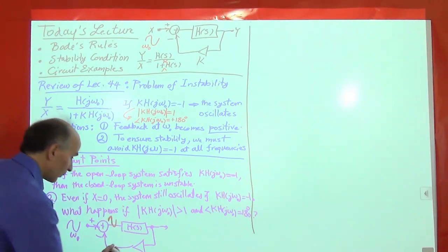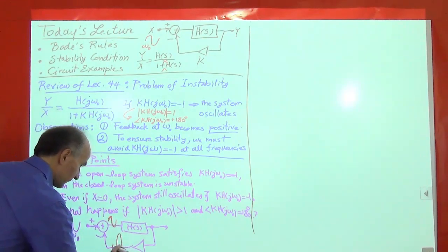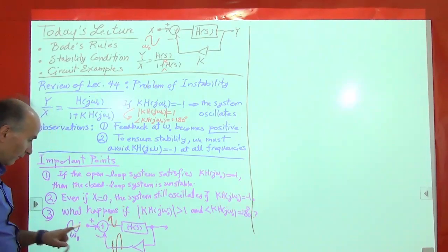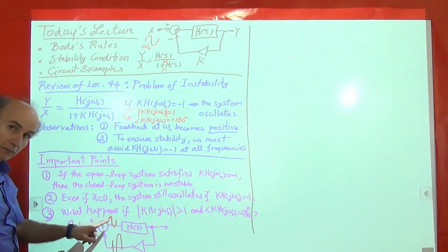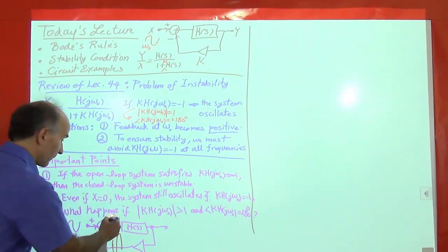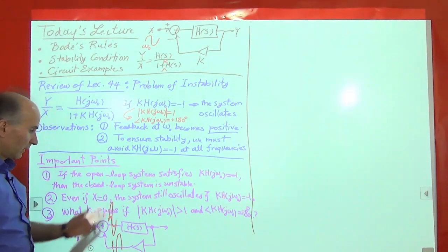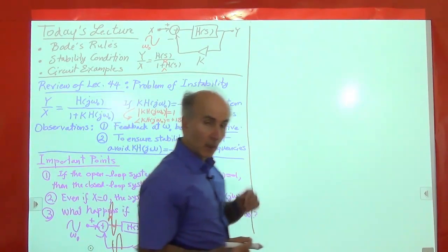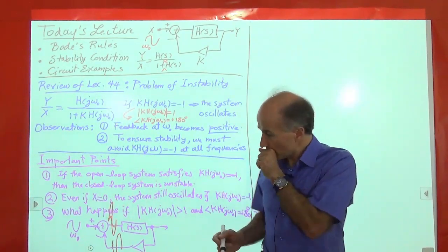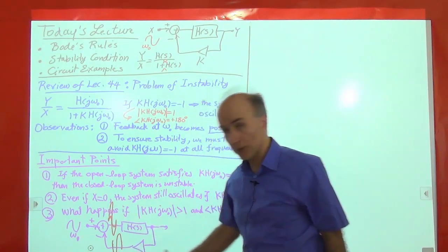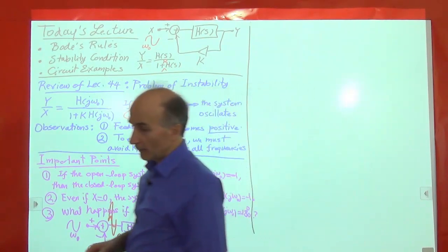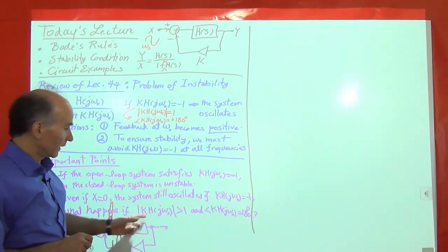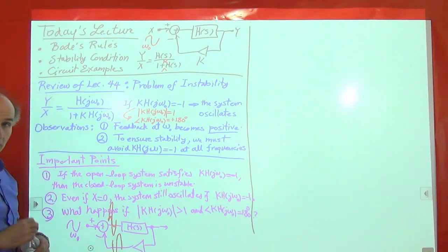So this will be larger. Now if I subtract this feedback signal from the input signal, I will get something even larger, right? So this will come even larger, and this will just circulate around the loop and will turn into oscillation. So we see from this simple description that even though the magnitude is greater than 1 for kh, we still have an unstable system.